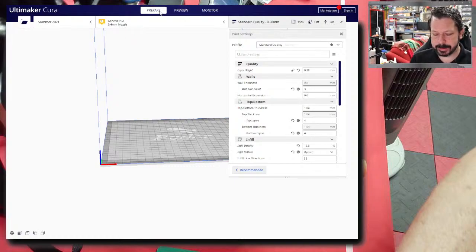So I don't think that one's one that you need to worry about too much if you can't get the terminals to work. It's where you can send G-code directly to your printer. The first layer, obviously, that's important because you can't even print if you don't get the first layer right. There were a couple of comments in the Discord about print sticking, like you print it and you just can't get it off of the bed.